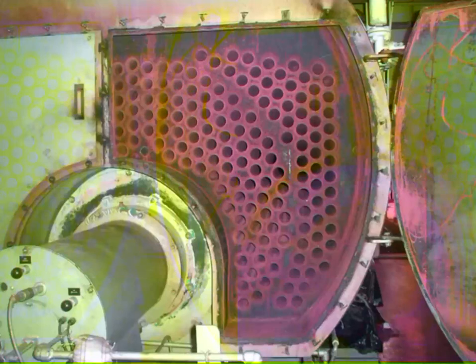You would have to do every single tube, and then you go into the back, and there's an opening that you can get in, and then shovel the soot out of the boiler. This has to be done on a regular basis, and the frequency is dependent on the fuel and how much soot is going to be left behind. Typically, this isn't that big a disadvantage for most motor ships because when they are at sea and underway, the boiler is shut down and you are on your exhaust gas boiler. So this can be a normal maintenance item that is done out at sea.